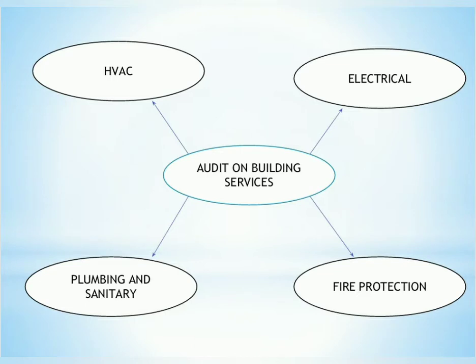For the chiller plant, the problems are compressor problems, insufficient cooling flow, chilled water pipe and condenser leakage, and condensation. For the cooling tower, the problems are biological fouling and a Legionella outbreak.